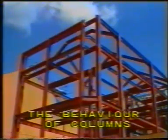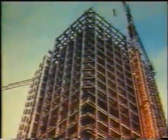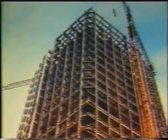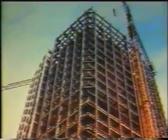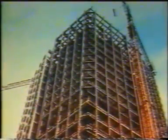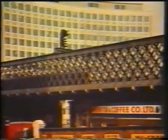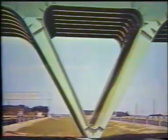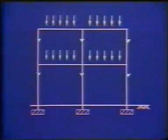Columns are the main vertical members in all types of building construction. The essential feature of a steel column is that it is a relatively long and slender structural member subjected to compressive loading. Other similar steel members can be found in the compressive struts of trusses and the supports of bridge structures. In buildings, the primary purpose of the columns is to transfer loads from the floors and the roof to the foundations. They hold the floors apart.